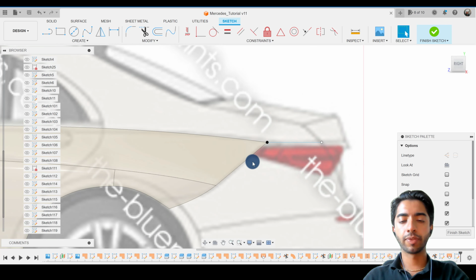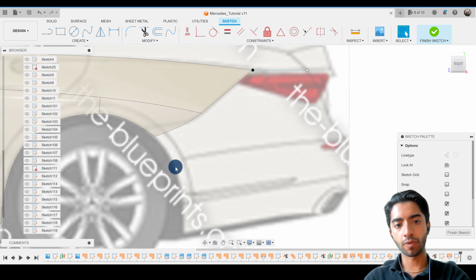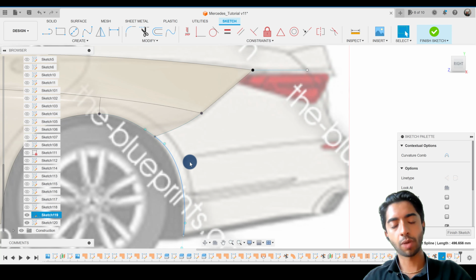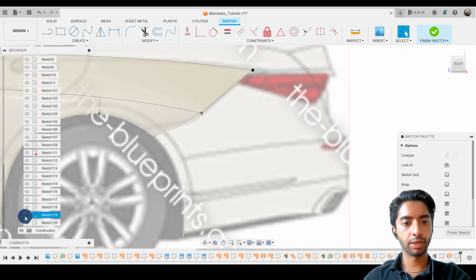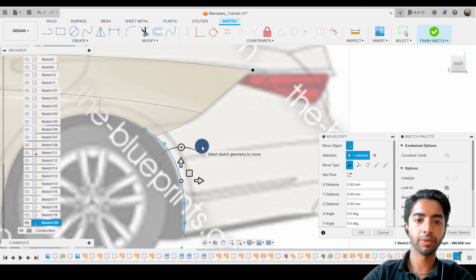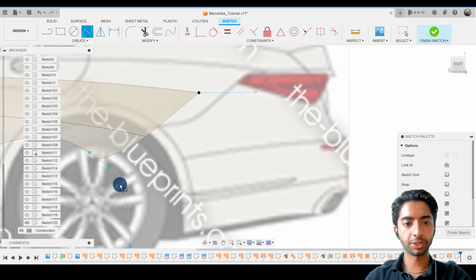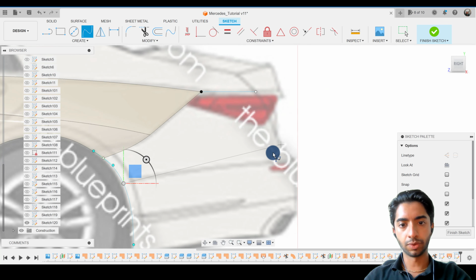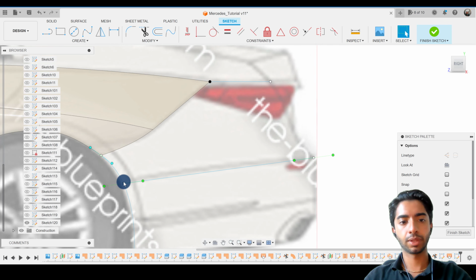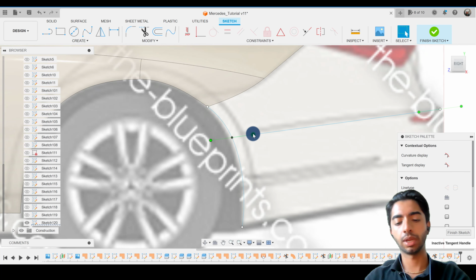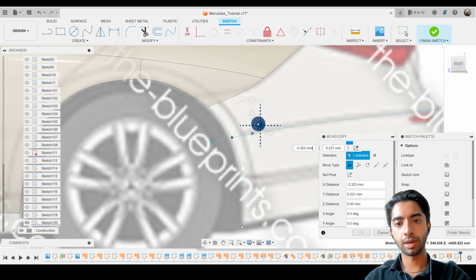Cool, now that we have that in place, the next thing I want to do is add a little bit more curvature here. So we want to create a point from here to here. And remember, in the last sketch, we had created a little bit of an arc. So let's copy that arc, hide it back, and paste it in this one. So there we have it. And what I want to do now is, again, a fit point spline from somewhere here to there. So from somewhere on the arc, go to the right, and somewhere there. So all I've done is just attach a new point on this arc that we had created from the previous sketch, and I copied that one in. So just add a little bit of curvature here.